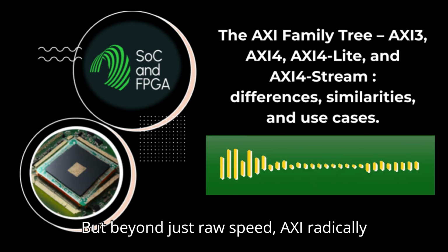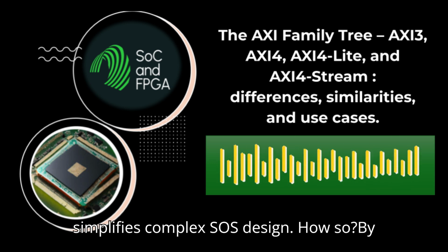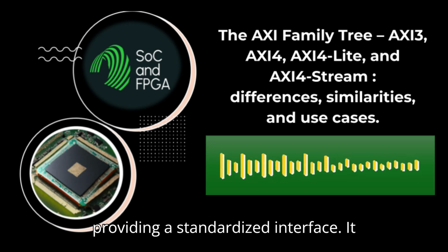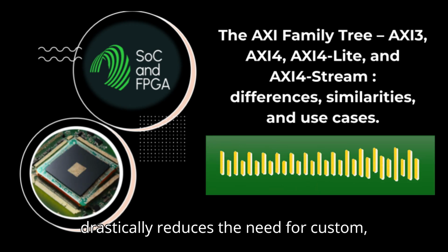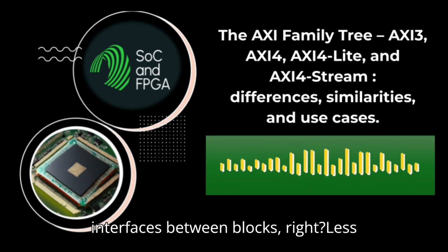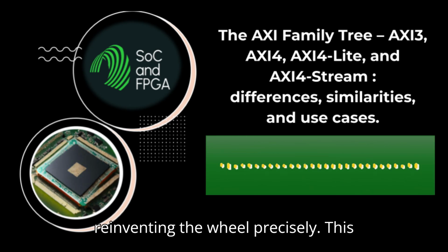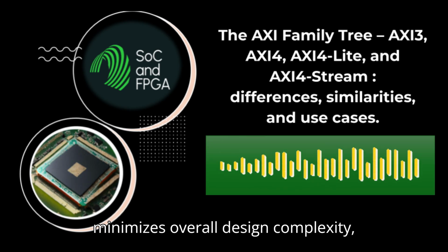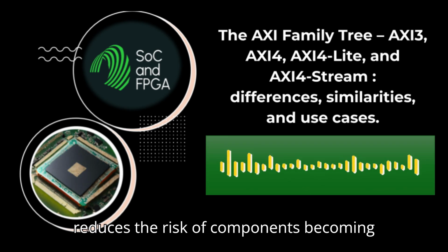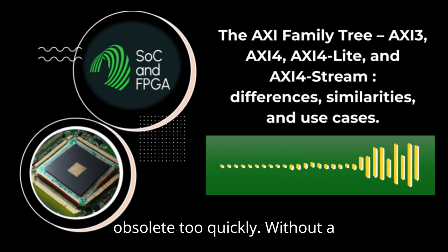But beyond just raw speed, AXI radically simplifies complex SoC design. How so? By providing a standardized interface, it drastically reduces the need for custom, one-off communication interfaces between blocks. Right, less reinventing the wheel. Precisely. This minimizes overall design complexity, which in turn improves performance and reduces the risk of components becoming obsolete too quickly.